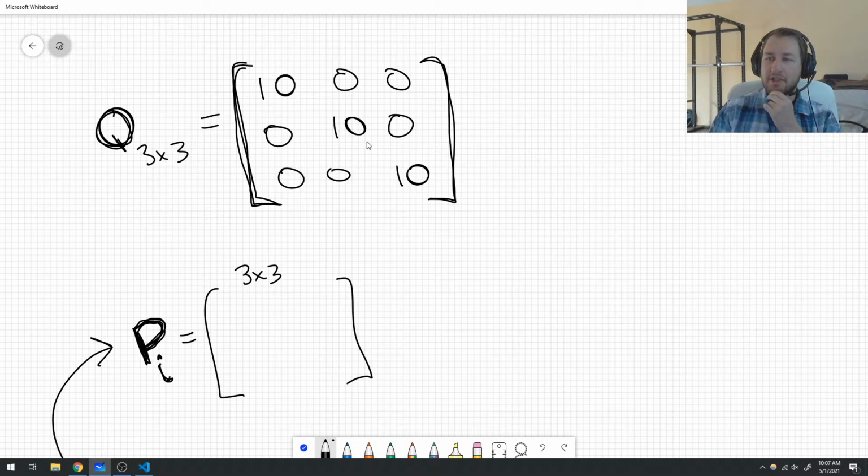This is how much variation you think there's going to be in each of these terms within the next time step. So these should be scaled based on your time step. If your time step is very short, you don't actually think that in 10 milliseconds your rocket's going to be at this value.